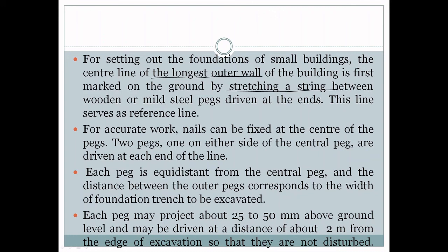If we fix the two sides of the right angle triangle, then the third side should be taken. The dimension should be set out with a steel tape. The alternate method of setting out a right angle is by the use of a theodolite.